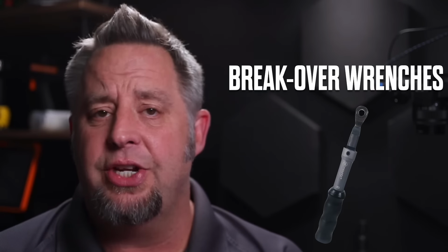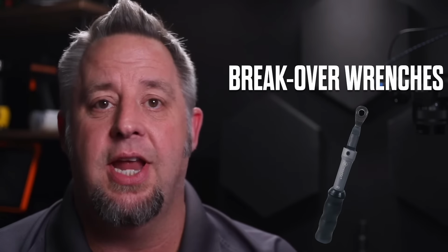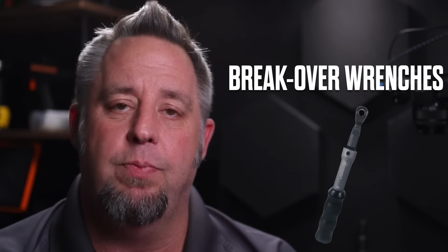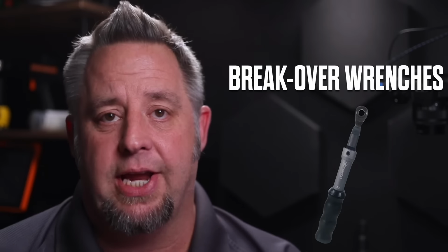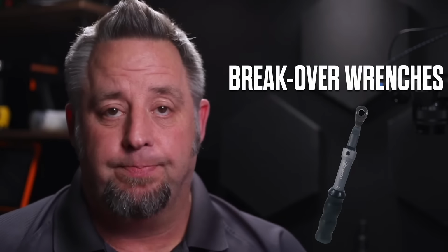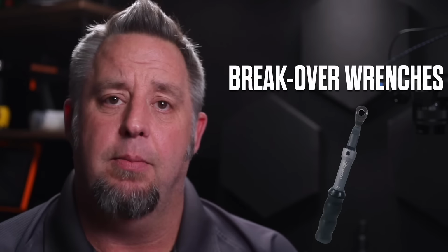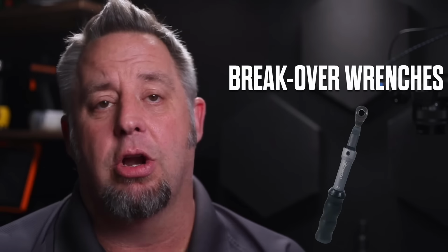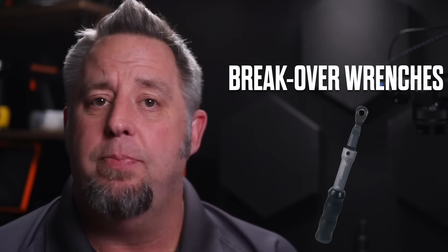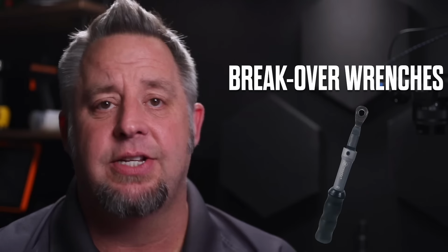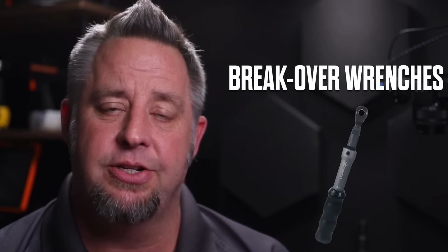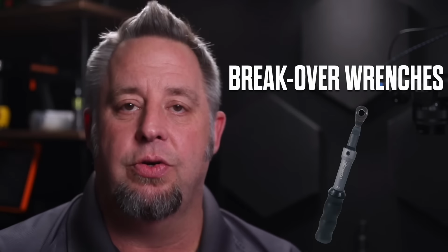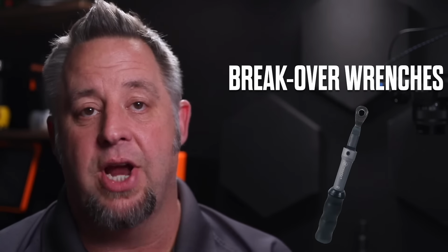And so this wrench basically does what the name implies. Once the wrench meets its particular torque value, the head mechanism will begin to break, or break over. And that can be a maximum of 90-degree break. Could be set with a collar to 20 degrees. So basically, as the operator is using that tool, once the wrench begins to break, you know that they've hit their torque value, and you've got a much greater window to stop pulling on the wrench.